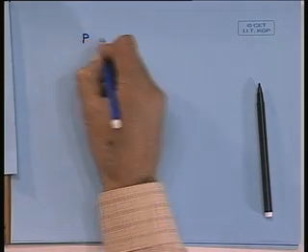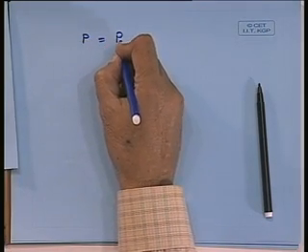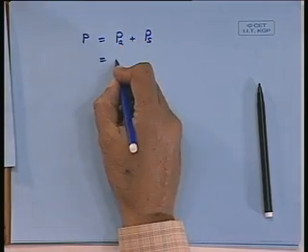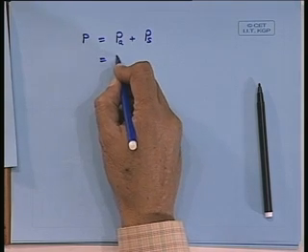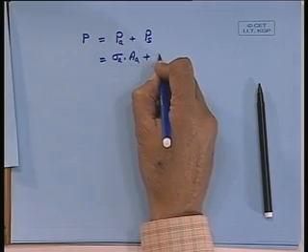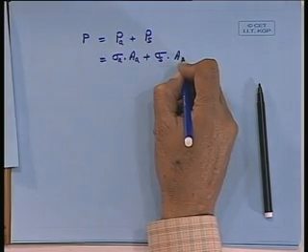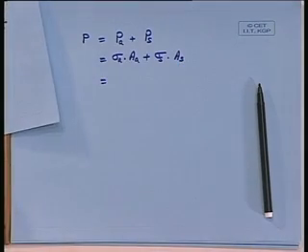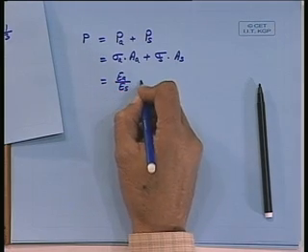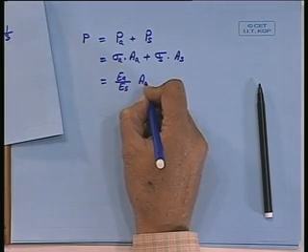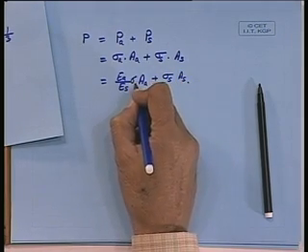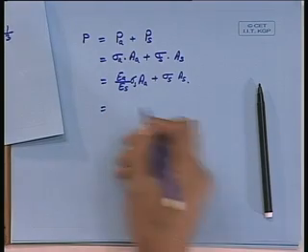So I can say that total force is equal to P aluminium plus P steel. What is P aluminium? It is sigma in aluminium into area of aluminium, and sigma in steel into area in steel. What is sigma aluminium? Now let me substitute from here. Sigma s let me take out.